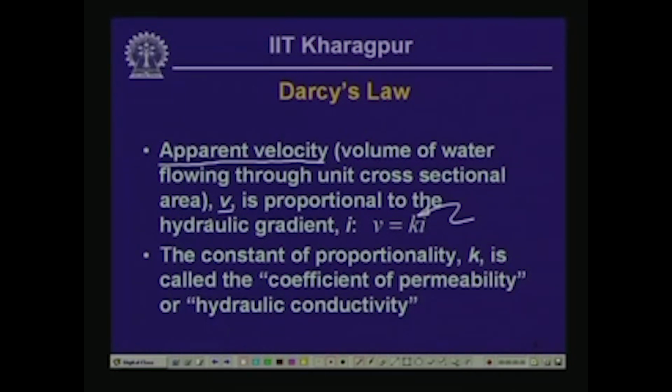Why that is going to be different is because the length of the route travelled by groundwater through the aquifer is going to be different from the straight line distance from the inlet to the outlet within the aquifer, because of the tortuosity of the interconnected void space.